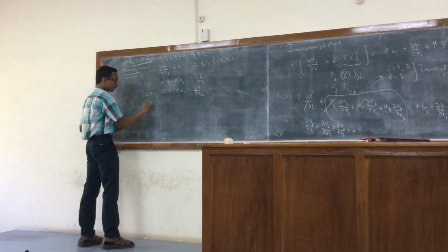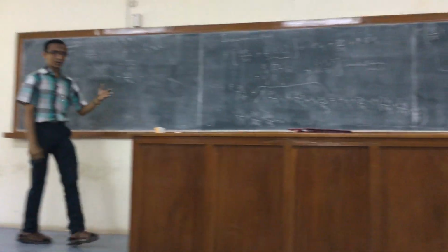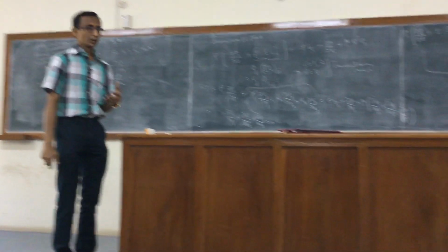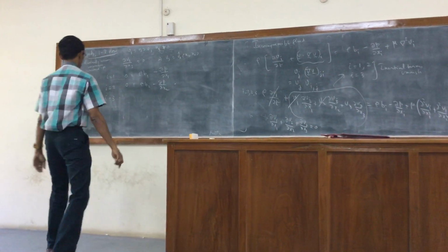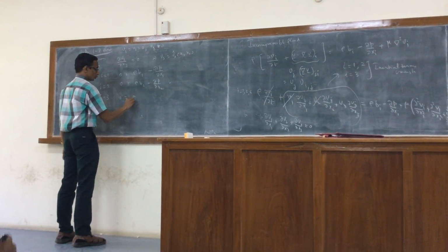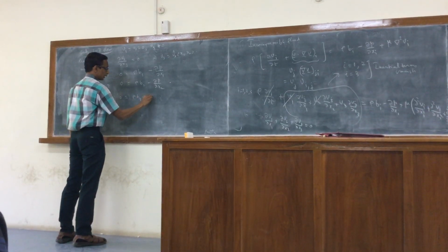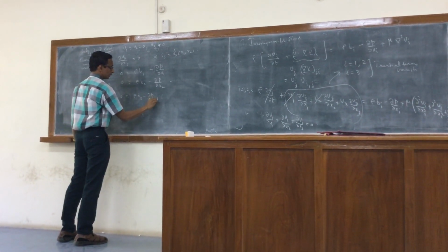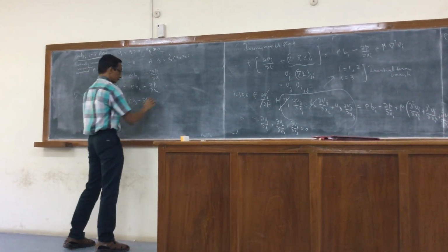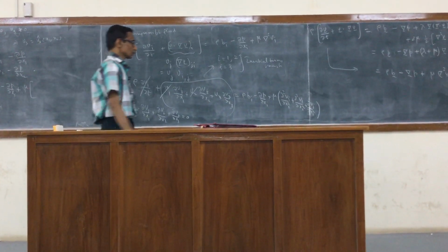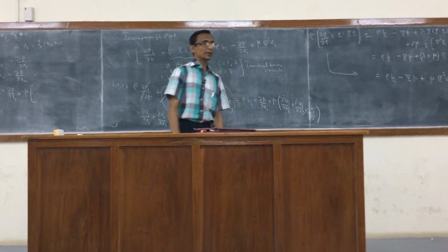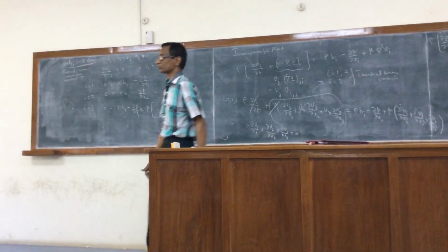And for i equal to 3, the left hand side will continue to be 0 for steady flow, and we have shown that the inertial terms will vanish. And we get 0 equal to rho b3 minus dp by dx3. So b3 cannot depend on x3.